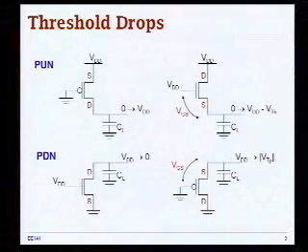So now we can also consider a case when PMOS transistors implement pull down and NMOS transistors implement pull up. Let's go back to slides actually over here. I have it illustrated over here. So when you have a pull up with a PMOS transistor, then we know that PMOS is really a good pull up device. When the gate is low, this signal turns on the PMOS, then you can get rail-to-rail swing. So you can pull up this output from 0 to VDD.